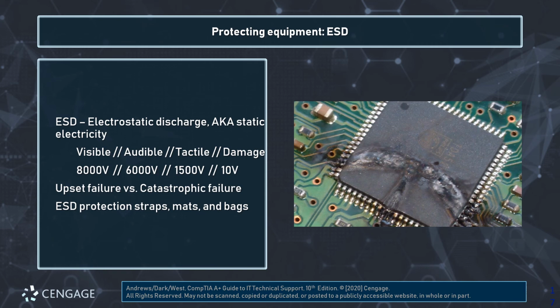Just to the right of the center, where the three things have converged, is the model number, and it's a Philips chip. Right there you can see 2 or 3 points at which the discharge occurred, passing electricity into the chip from 3 separate areas, enough that it started to expand and ripple outwards and cause these char marks.